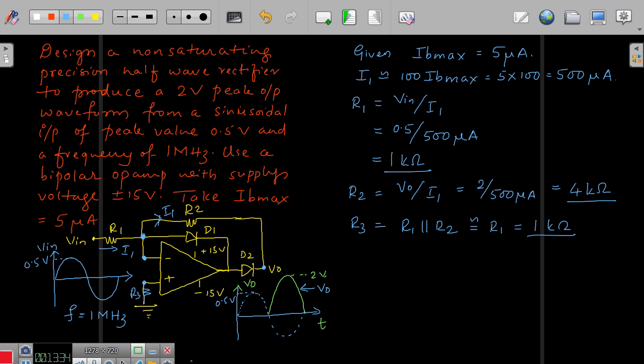So that is the reason why we are using this resistance sometimes. Even if you do not use this resistance, for a certain operational amplifier it works, right? You can always take the biasing resistance which is equal to R1 here, or very specifically the parallel combination of R1 and R2. So you can take it as R1 here now, which is equal to 1 kilo ohm.